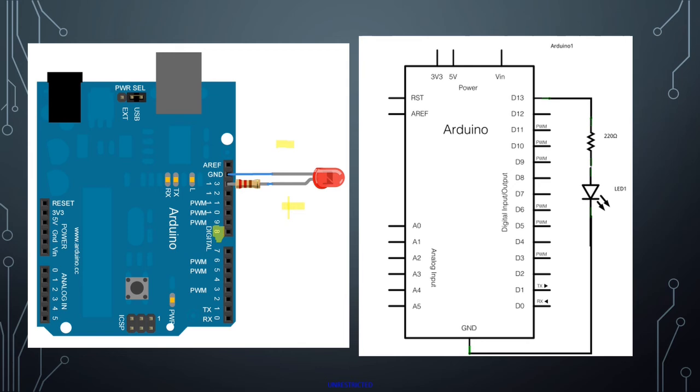Okay, and then it's the exact same thing represented over here on the wire diagram. It just looks a little bit different. And now I'm seeing, so this is connected to pin 13. I told you this was pin 3 over here on the left. That was my mistake. It's actually pin 13. The way this is written is just a little odd. So this is actually pin 13. So same thing, pin 13, you see we have a resistor here.